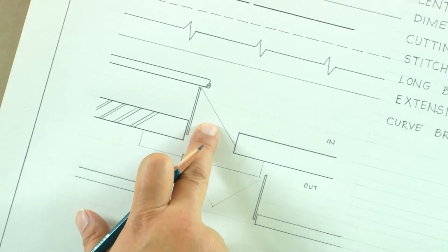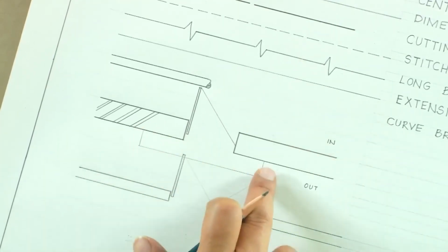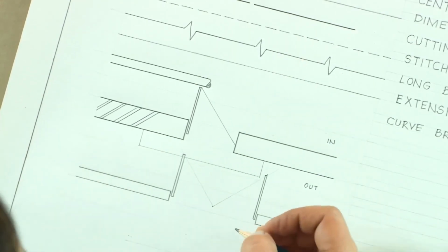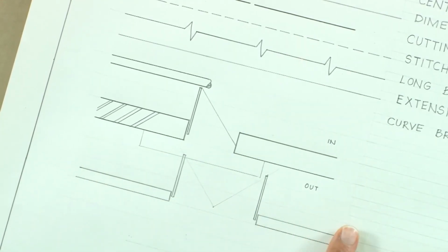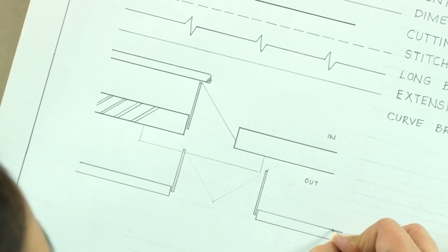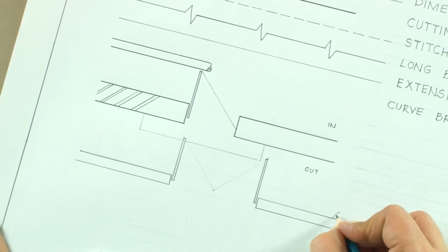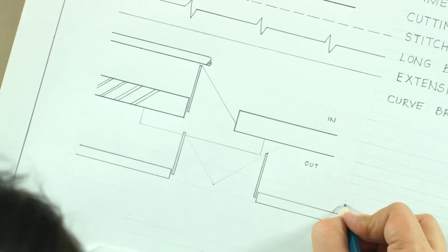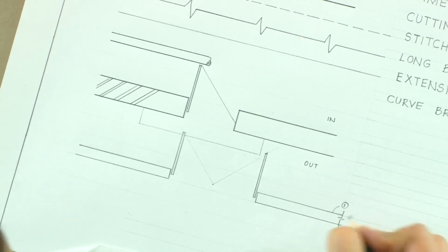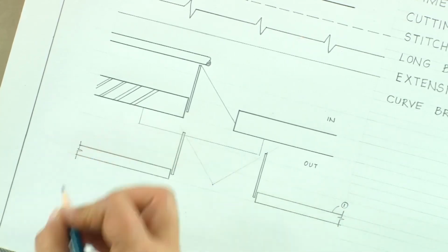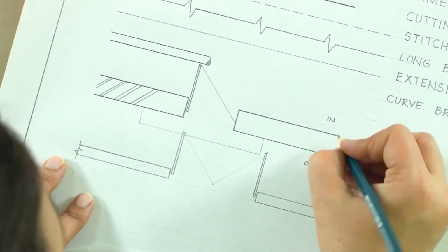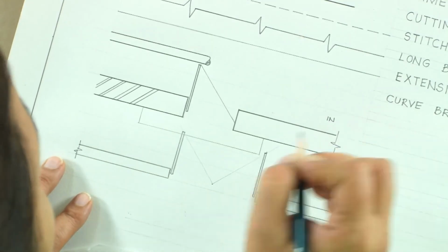So this is the representation for a double door. This is a single door only inside, single door outside. This is the representation for a double door which is opening like this. And when you are drawing this kind of drawing, please mind the level of darkness. This line is going to be the darkest. If I write in a descending order of darkness and thickness, this is the darkest because this is brick in section. And please remember that you will have to draw section lines on both ends of the brick. So you will draw section lines on both sides, whether it is here or wherever.